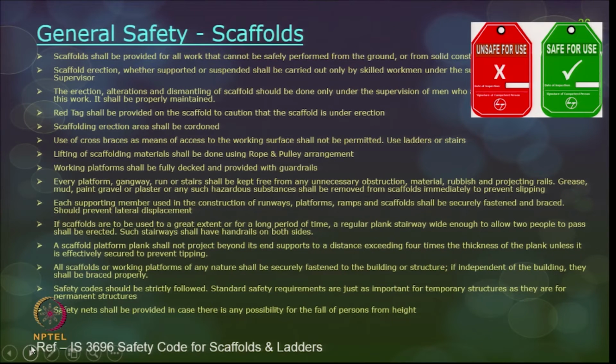The erection, alterations and dismantling of scaffold should be done only under the supervision of a competent person, and even the maintenance of the scaffolds should be taken care of properly. When the scaffold is under erection, it should have a red tag which says unsafe for use. And the scaffold erection area should also be barricaded, so that the public are not disturbing the scaffold erection, and also there is no hazard happening.